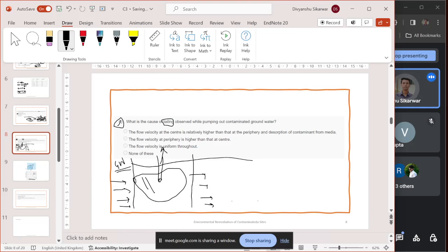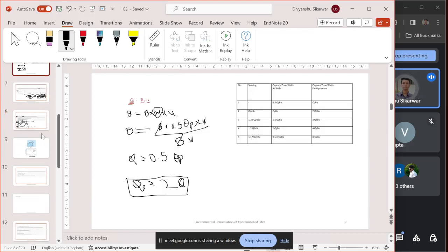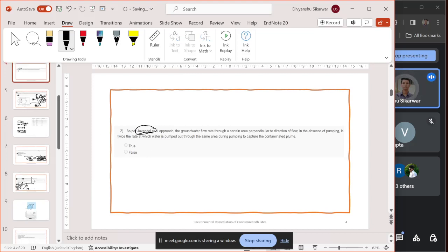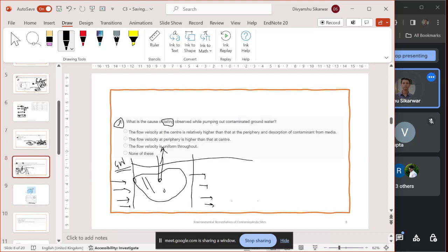If we scientifically design it, we can design the location of the well and how many wells we require. All these things are in the week 3 lectures, and how we design those wells is given in a particular method. This approach is used to determine the spacing of wells and the zone of influence for each well.